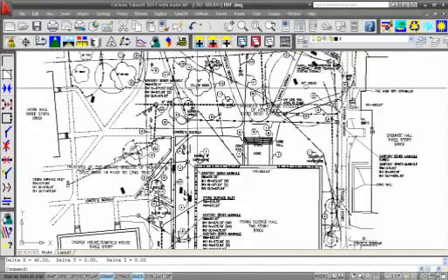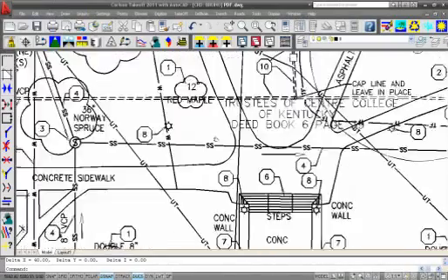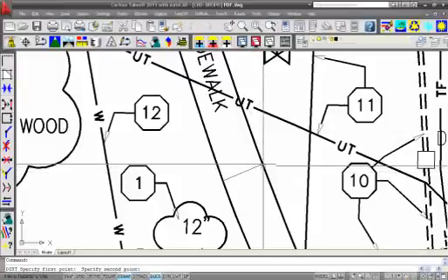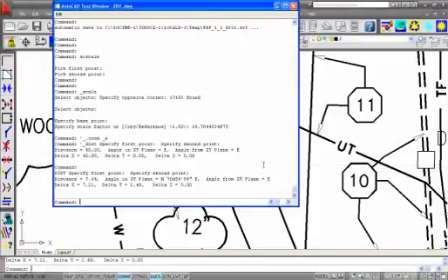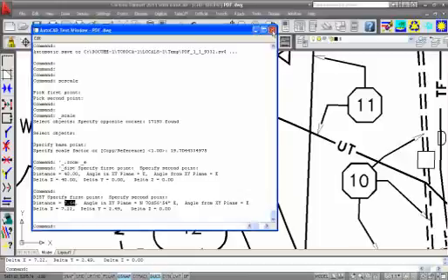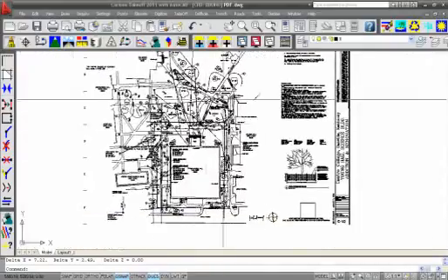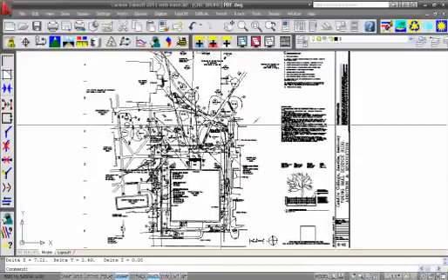If I want to check the distance actually on the job, let's go back to our asphalt block. Standard distance again, going across here, F2. Now that's over 7.5 feet wide. Makes a lot more sense for a walk as opposed to under half a foot. So we've now scaled this PDF accurately. That 2D scale is a lot quicker way to calculate that scaling factor.